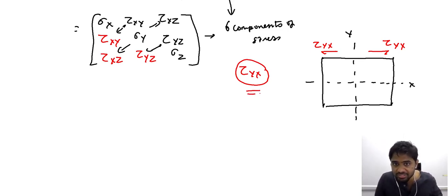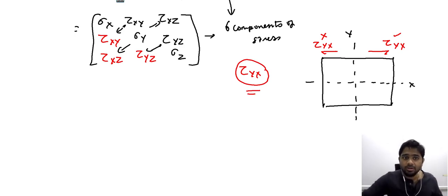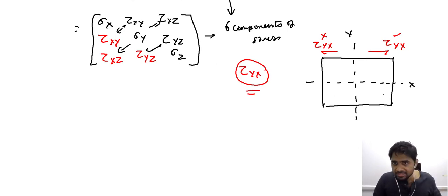Even though we use the same term or the same parameter, these are acting in two different directions. Therefore, we need to distinguish one stress from another. We need to distinguish these two stresses, one acting in this direction from the other acting in the completely opposite direction. So how can we do that? This is where the convention associated with the shear stress comes into play. Now for the case of the stress square, let us consider all the shear stresses that we were able to introduce in this stress square.